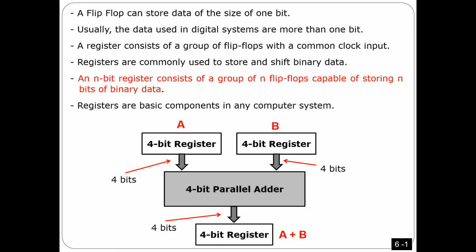Look here, for example, you remember the 4-bit adder I explained in chapter 4. Now I want to add 2 numbers, and then store the result somewhere. To create a complete system, usually I need a storage for a number of bits, register A. I need another register, for example register B. These registers are connected in hardware to the adder, and then the output of the adder has to be stored somewhere in another storage unit.